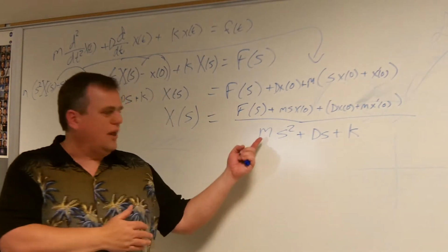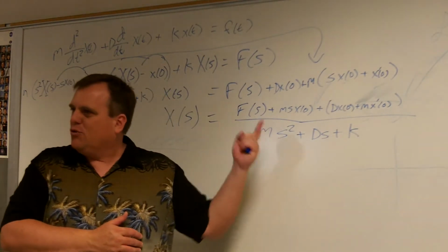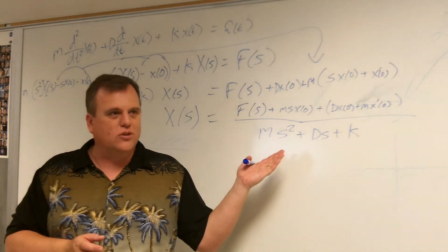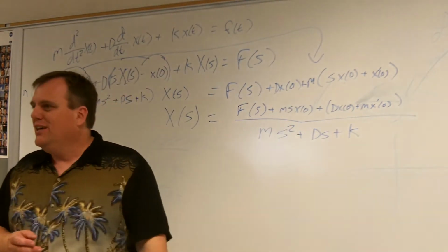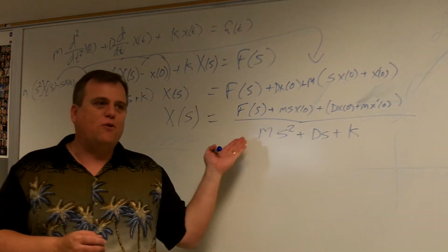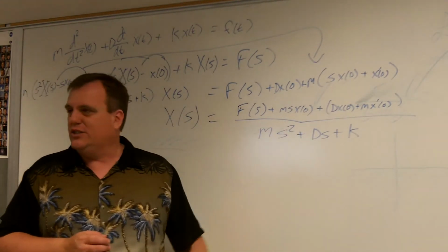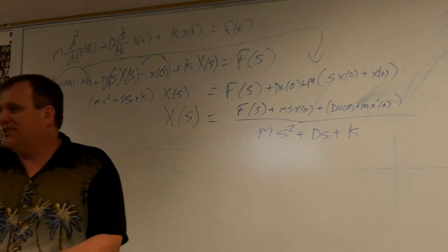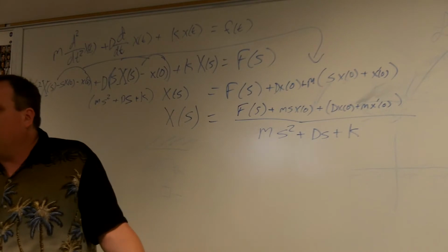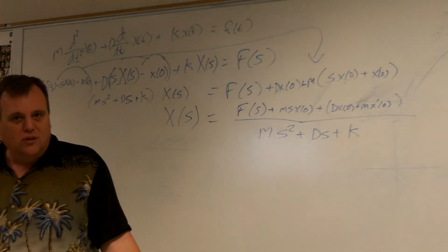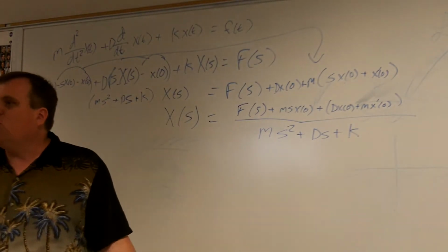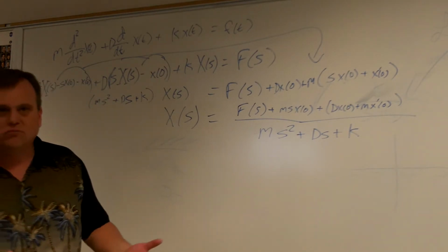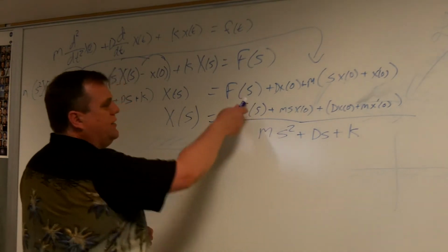If I don't normalize this, I have to write really ugly looking expressions where it's hard to find the powers and things of that sort. If I normalize, I can have all of my tables start with the highest power of S equal to 1. So it reduces the complexity of the table a little. Since we want to do things by lookup, it's a lot easier. It makes a lot more sense. So this next step is to make my life easy for later on down the line. So what I'm going to do is divide top and bottom by m.